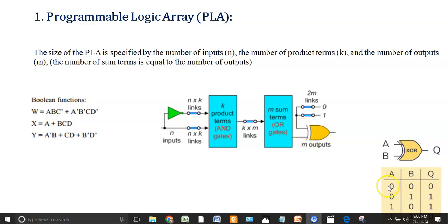If I have connected one input of the XOR gate to 0, that is over here, suppose this is 0 and this link is closed, so I have connected it to 0, meaning whatever comes on the second terminal, here mentioned by B, the same output you will be getting over here. So if I am having 1 over here, I'll be getting 1, so there will not be an inverted output. But if I want my logic to be inverted, that is my requirement, and I don't want to use an extra NOT gate over there, that will be done through this XOR gate.